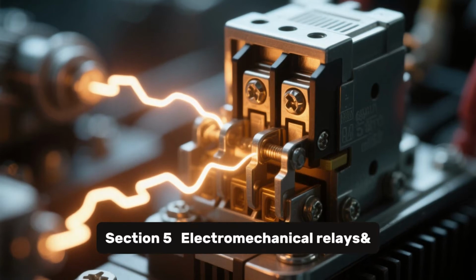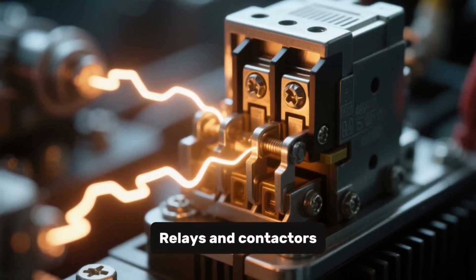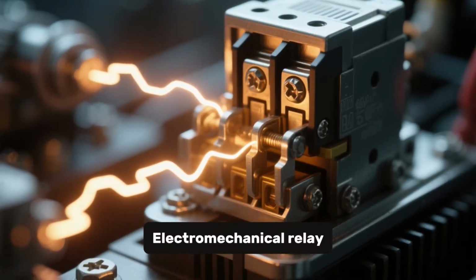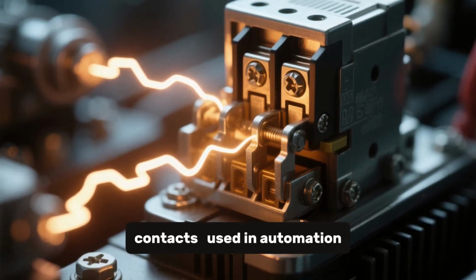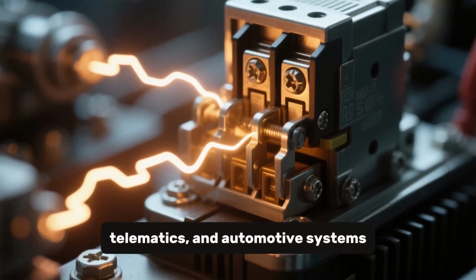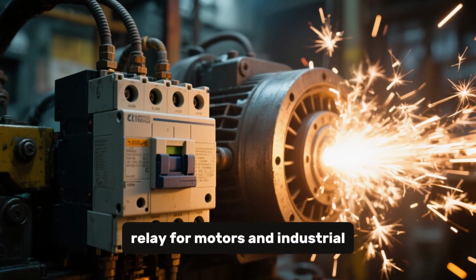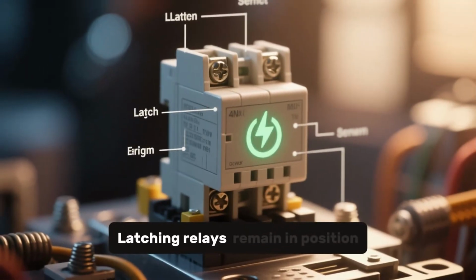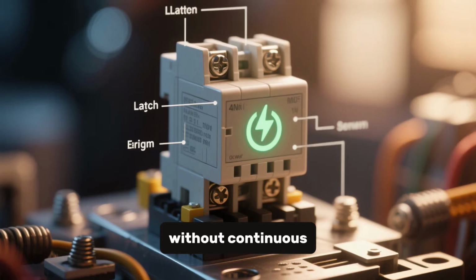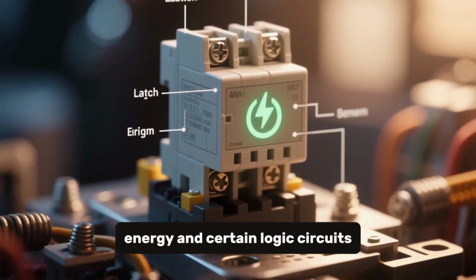Section 5. Electromechanical relays and contactors. Remote switching. Relays and contactors let low-power circuits control high-power loads. Electromechanical relay: coil energizes to close contacts. Used in automation, telematics, and automotive systems. Contactor: heavy-duty relay for motors and industrial power switching, often combined with overload protection. Latching relays remain in position without continuous coil power. Useful for saving energy in certain logic circuits.